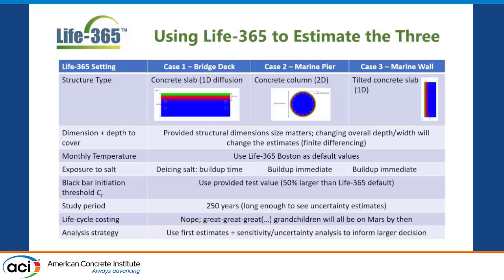And so then the call is like, well, I didn't change the depth of the cover. Why am I getting a different service life for a different depth of slab? It's because, as modeled, it's modeling a concentration high, a gradient down to no concentration at the bottom. So the deeper you make the slab, the longer the gradient and the more time it takes to pull. It's just a different pull than if it's 8 inches or 4 inches, so you will get slightly different answers. It shows how the model isn't necessarily a perfect representation of reality, but that's okay. I've got a blanket statement to say about that later.